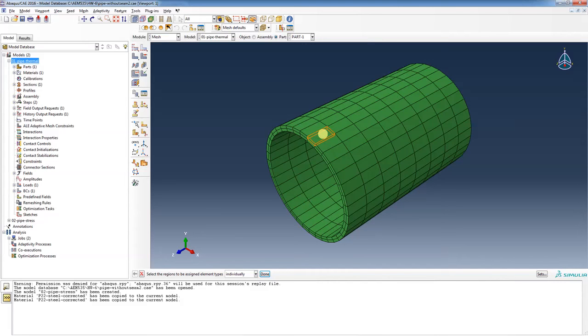If there was a cool breeze on this pipe, you can set up a convection coefficient on the exterior of the pipe to take that heat away. Now in reality, in most power plants, there are insulating jackets around these pipes. You really want to keep all that energy in that pipe. You use that to drive the turbines. So we're not going to put a convection coefficient on the exterior of the pipe. That's going to be like an ideal insulated area. But we are going to put a film coefficient or convection coefficient on the inside of the pipe.